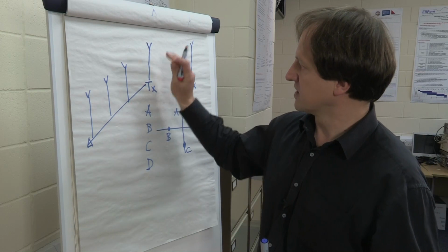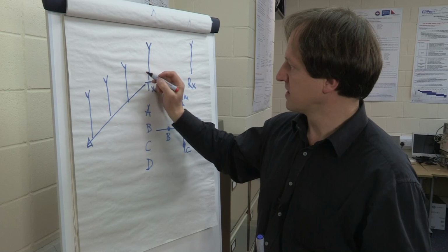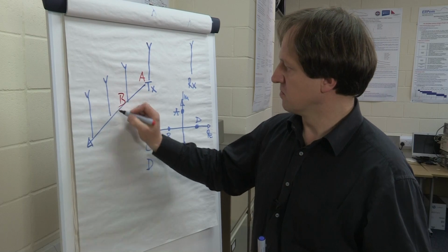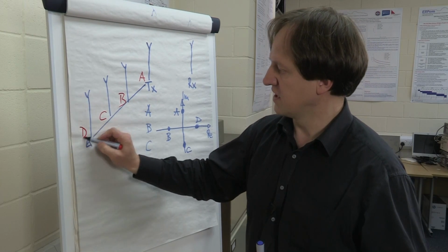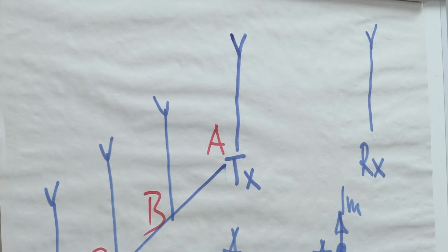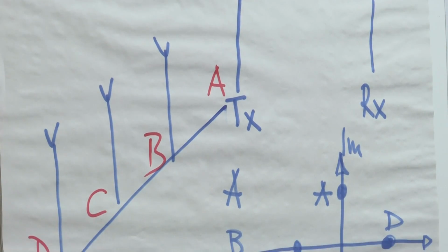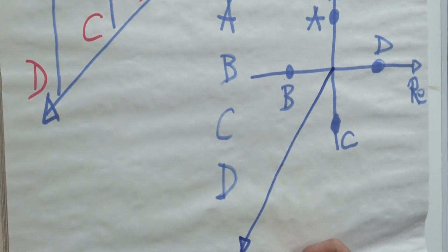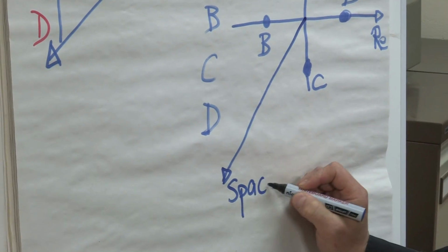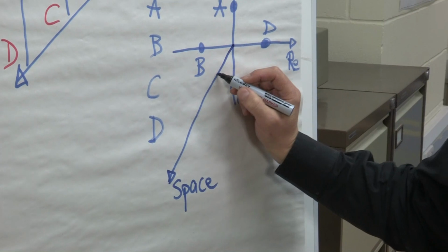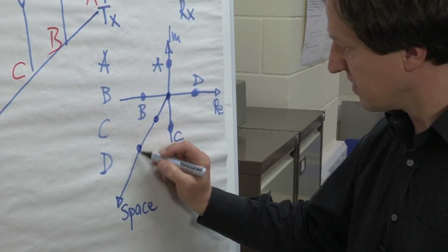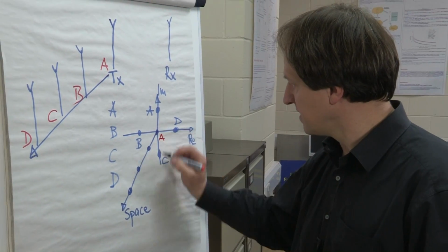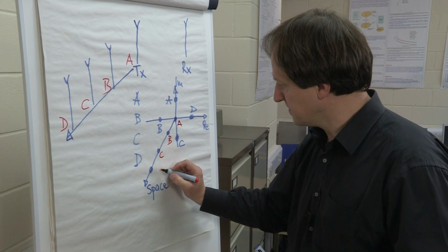And we say that, for example, that position here, that first antenna is linked to, again, the same symbol A, the second antenna to symbol B, third C, and the fourth antenna to symbol D. So essentially what we have created now is a 3-dimensional constellation diagram. And we can extend that diagram here into a 3rd dimension. It's called space, where we have the antenna constellation points, or spatial constellation points put here. And we repeat that. Say this is A, this is B, C, and this is D.